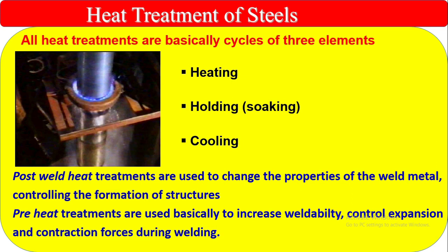If preheat is not applied, then the cooling rate will be very high, the expansion and contraction forces will not be controlled, and that area will definitely crack. That's why preheat is always a mandatory requirement.